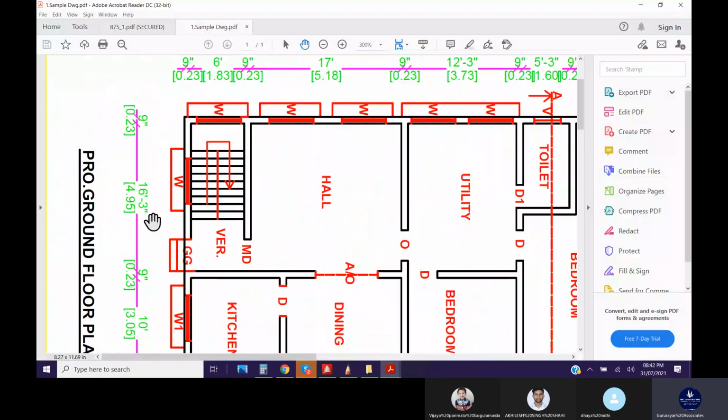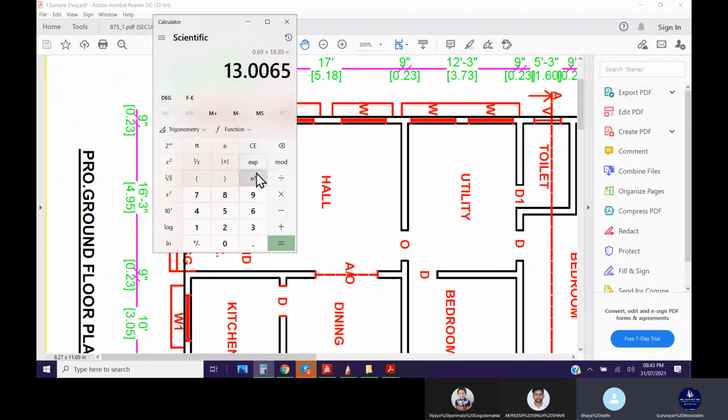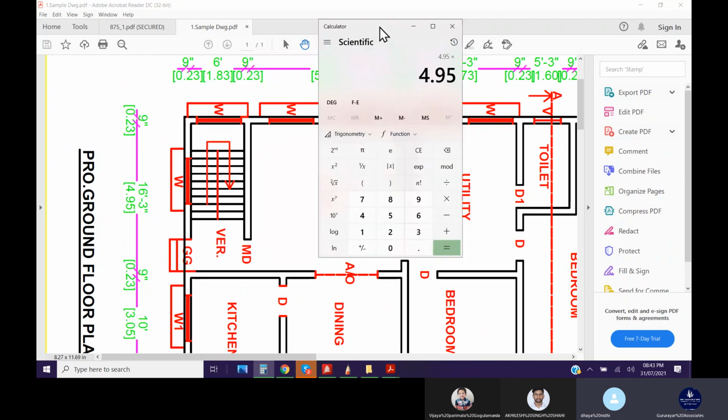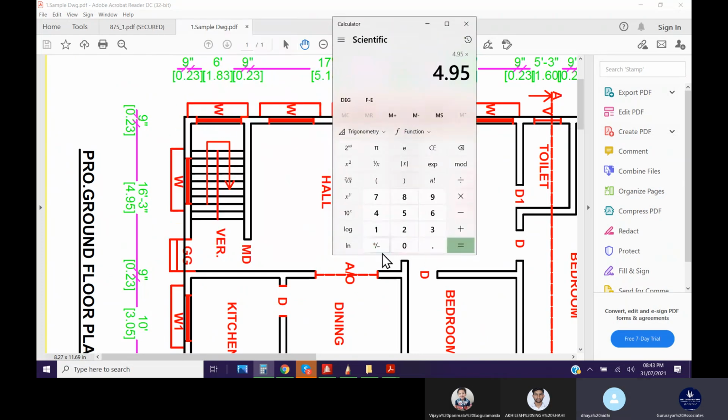Staircase room length is 4.95 meter. Okay, approximately. Center not required, just take 4.95, outer to outer. 4.95 meter multiplied by the width of the staircase room, 1.83, inner. 1.83 multiplied by the height, 2.5 meter, the water tank height. So it gives 22.64 cubic meter.